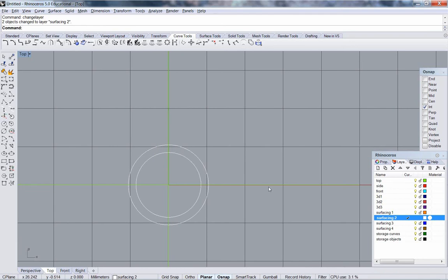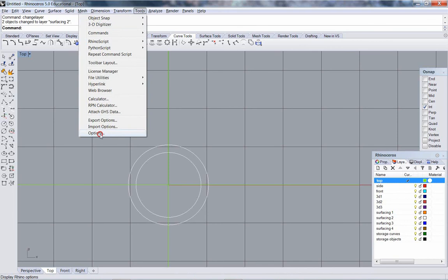I want to carry the same information that I've got so far into the top and the side. Always work your drawing as far as you can equally as you go. So, all the way around. I know my band is going to be 3 millimeters wide for the stones, 1 millimeter each side for the rims. That's 5 millimeters. I know these grids are set 10 millimeters apart. I know that because I set them in options,